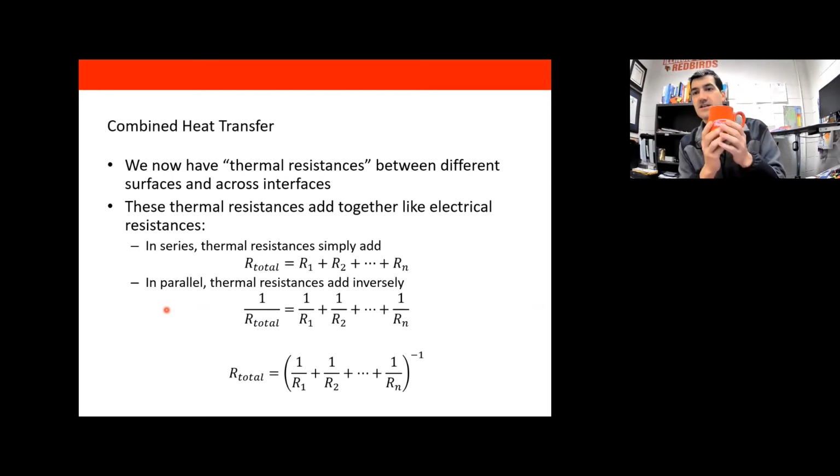But if you've got a good example, like a hot object in the middle of the room, then you're almost always going to have both some type of convection and some type of radiation happening simultaneously, which means they're in parallel. So if we have that situation, we can combine them in parallel by just adding them inversely. And remember, we have 1 over R total equals 1 over R1 plus 1 over R2 plus ...